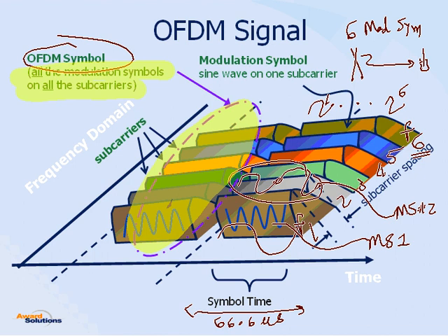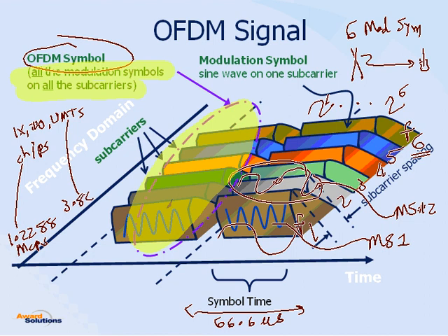In CDMA systems, could be 1X or let's say DO or UMTS, doesn't matter, what goes over the air is chips. How many chips per second? If it is 1X or DO, 1.2288 mega chips per second. If it is UMTS, of course, 3.84 mega chips per second.